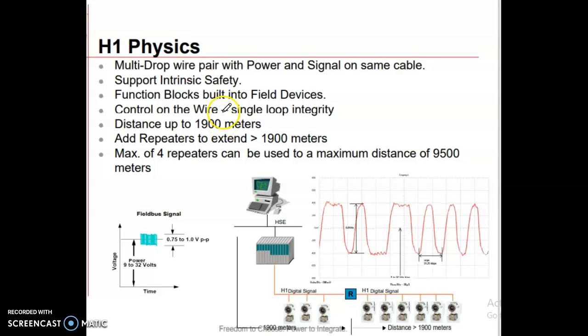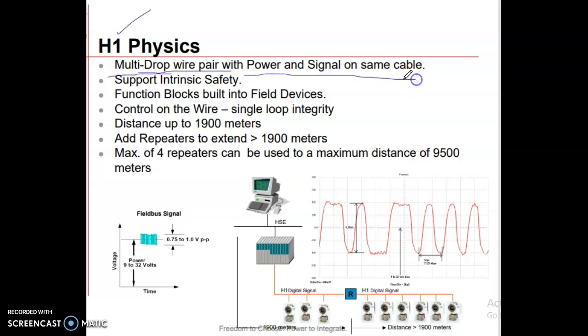H1 physics. Multi-drop, that is Fieldbus. H1 means Fieldbus here. Multi-drop wire pair with power and signal on the same cable. In this multi-drop wire pair, power and signal are on the same cable only, no need for a separate cable. Supports intrinsic safety.